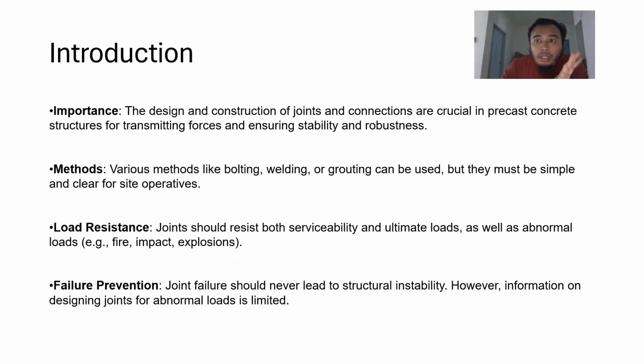So there are various methods: bolting, welding, grouting, or just simply placing, just to ensure that the components are in contact. There are various methods to produce a joint, but they must be simple and clear for site operatives to ensure the effectiveness of the joints.